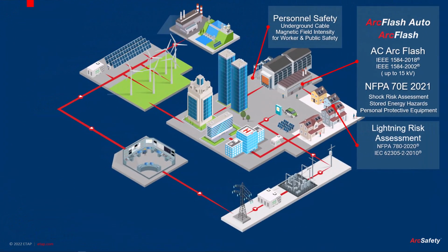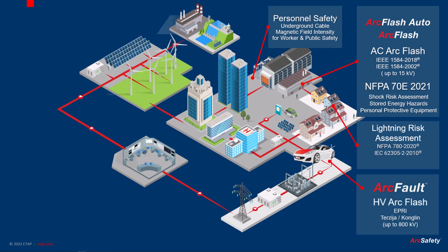Now let's switch to the joyride again and we will see how ETAP provides another solution for locations where the IEEE 1584-2018 method is not applicable. The official standard used to have the Lee method as the alternative method beyond 15 kV, but in the 2018 standard it was removed. Because of the overly conservative results provided by the Ralph Lee program, ETAP does have